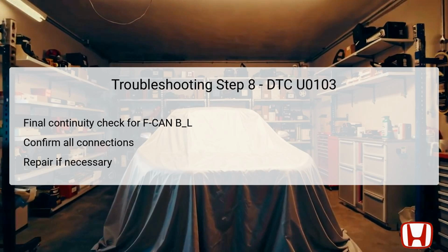If continuity testing fails, that signals the presence of an open wire needing repair between the SBW shifter control module and the TCM. Successfully completing this step verifies the repair of communication issues.